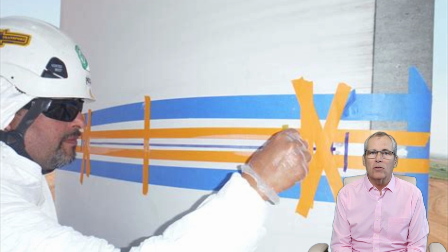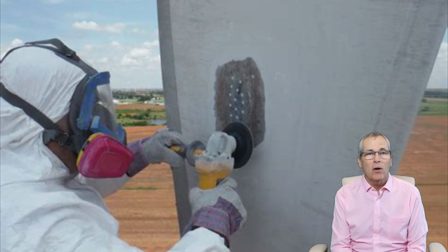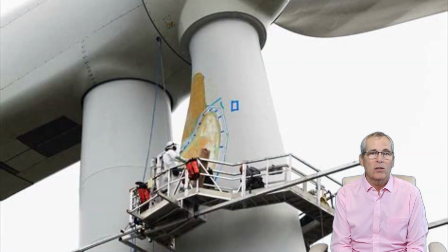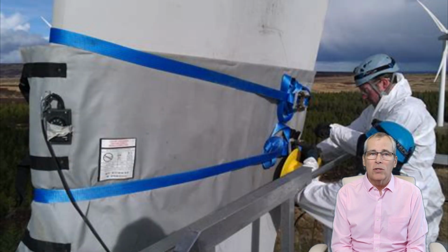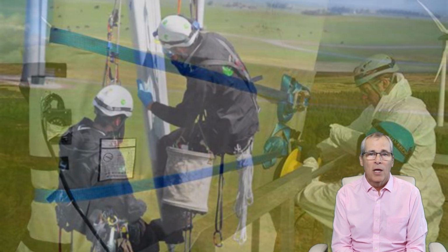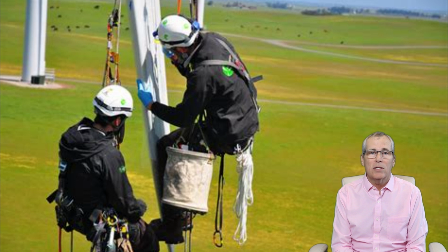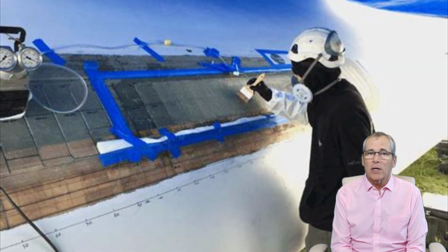If the blade is only slightly damaged, such as minor nicks or scratches, it can usually be repaired. Repairing individual blades can be a cost-effective solution, as it allows for the continued use of the blades that are still in good condition. However, it's important to keep in mind that over time, blades will naturally degrade due to exposure to the elements, and the performance of the turbine will be affected. For this reason, it's recommended to replace the blades in sets when they reach the end of their expected lifespan, regardless of their current condition.